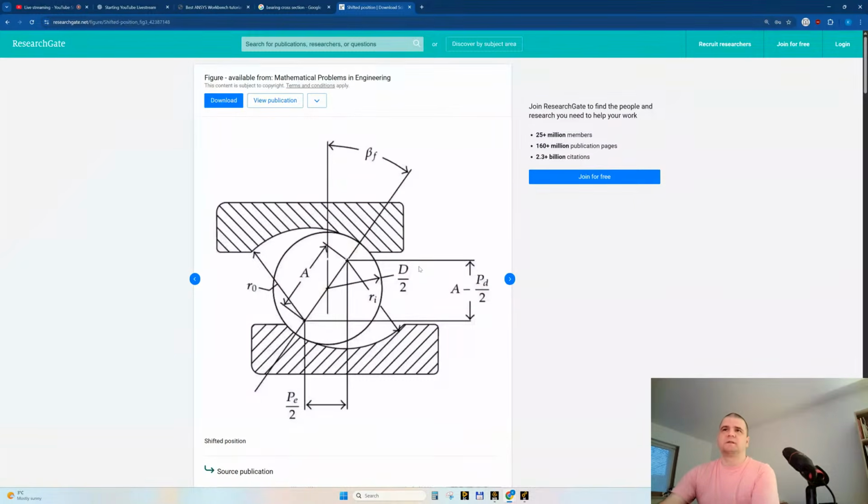But because we will only rotate a few degrees, 90 degrees, maybe 180 degrees, we will need to impose a higher frictional coefficient than in reality, because we don't have lubricant here, and we will not perform hundreds of rotations of the entire bearing in order to see some rotation of one ball or of certain balls.